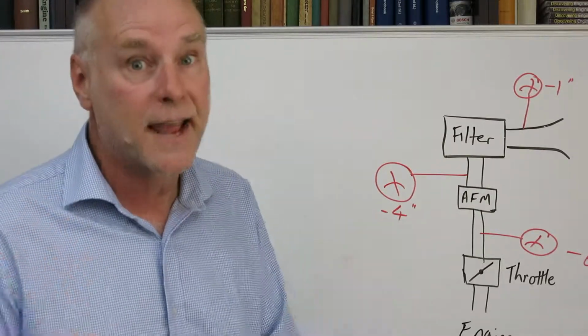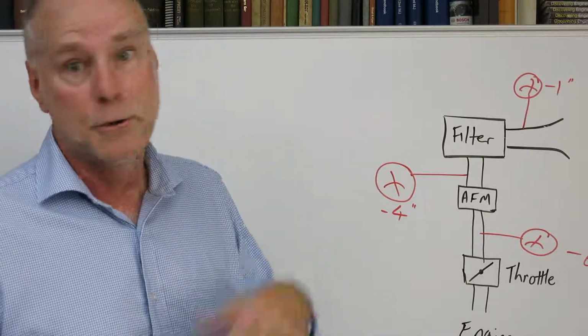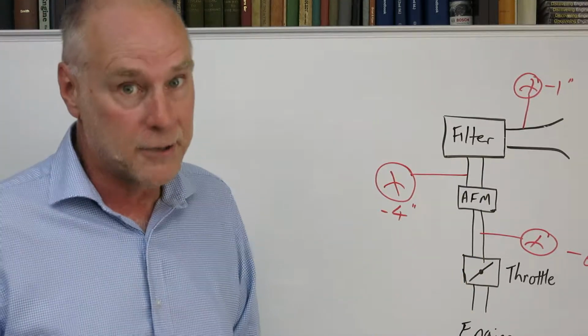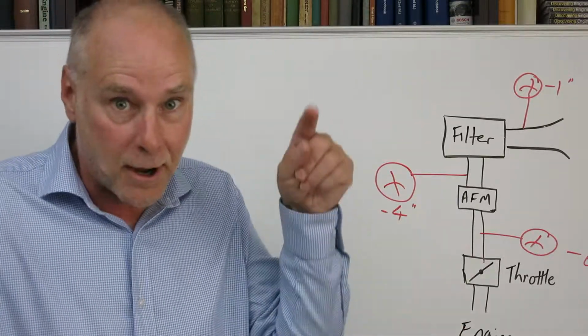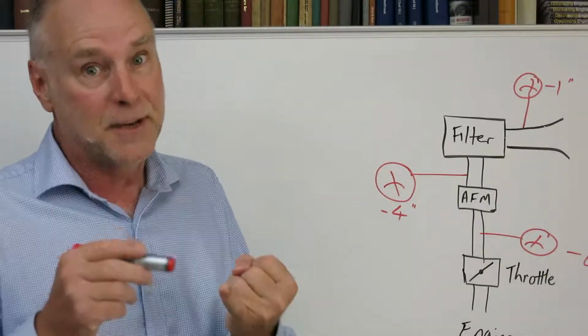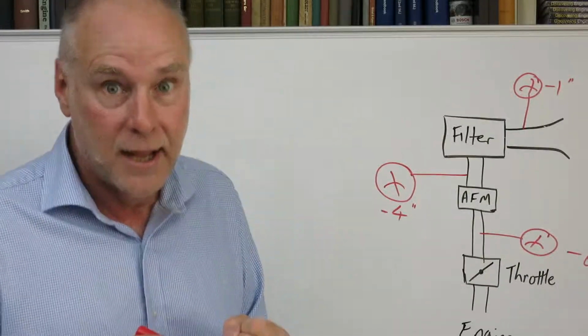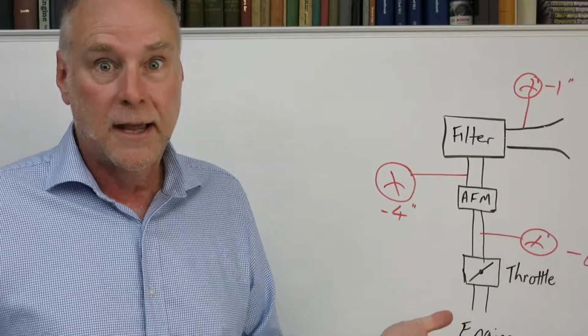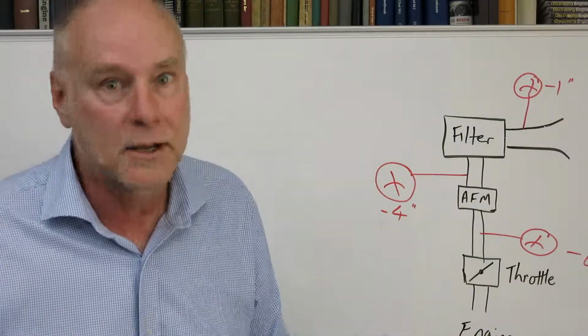Typically, if you measure a standard good condition filter in the factory airbox, you'll find perhaps only 1 inch of water pressure drop across it. I never change filters to high performance filters, high performance in inverted commas. Typically those filters have less filtering capacity, more rocks get into your engine, and if you're talking about 1 inch of water, even if they drop the pressure drop to 0, which they never will, it's only 1 inch of water.